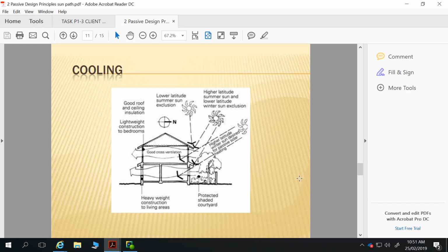So you've got to have air cell insulation between your roof sheeting and your steel purlins to stop temperature or loss of heat straight through those purlins into your sheeting and the condensation that results. So with the steel frame house, you've got to have that air cell insulation.